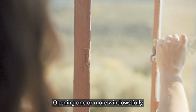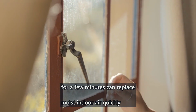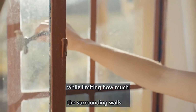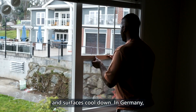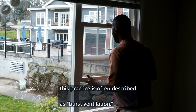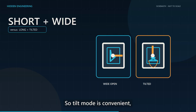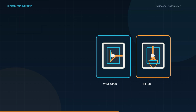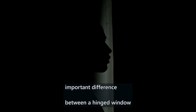Opening one or more windows fully for a few minutes can replace moist indoor air quickly, while limiting how much the surrounding walls and surfaces cool down. In Germany, this practice is often described as burst ventilation. So tilt mode is convenient, but it is not a magic energy-saving setting. During a cold German winter, full turn mode may actually be the better tool for a short, intense exchange of air. There is another important difference between a hinged window and a sliding one.